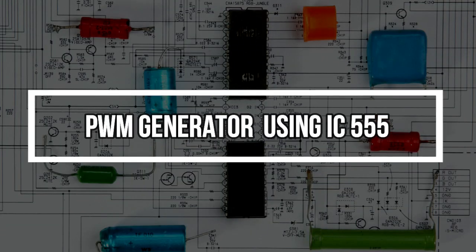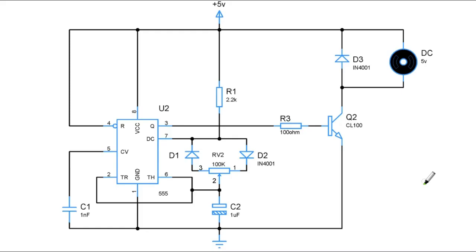PWM generator using IC555. This is the PWM generator circuit which we have built using IC555. If you notice, this is pretty much the same astable multivibrator with a few modifications. You can observe there is a resistor going from VCC to pin 7 and a capacitor connected to pin 2. Here the major modification we have made is we have replaced the resistor R2 with a potentiometer or a variable resistor RV2 and a couple of diodes D1 and D2.